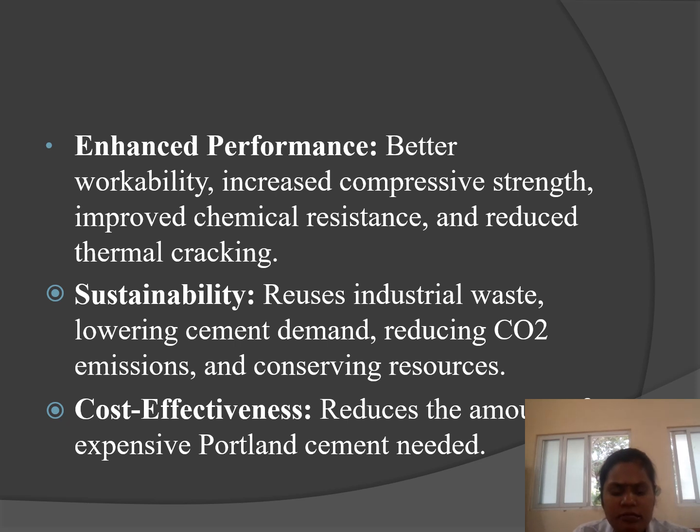Next one is enhanced performance: better workability, increased compressive strength, improved chemical resistance and reduced thermal cracking. Sustainability: reuses industrial waste, lowering cement demand, reducing CO2 emissions and conserving resources. Cost effectiveness: reduces the amount of expensive Portland cement needed.